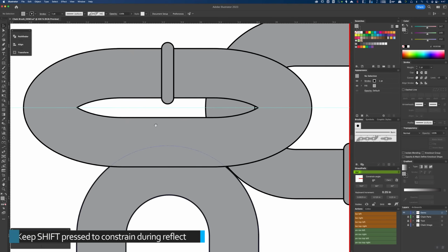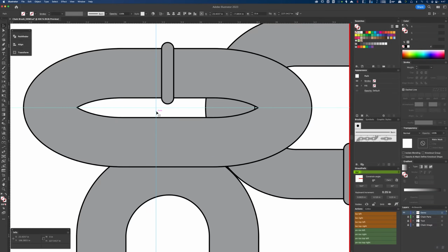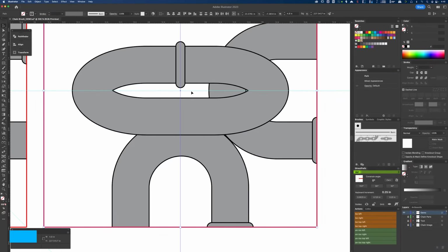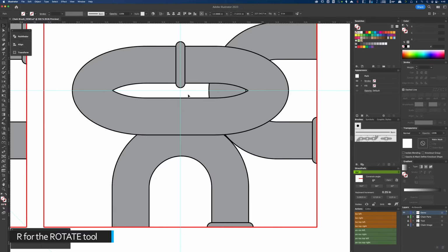Now I'm going to create our guides. So I'm going to create a center guide, drag select my box and the guide, click on the box to create our key object, and then click on horizontal align center. I'm going to drag down another horizontal guide, hit R for rotate, click in the center when it says intersect.